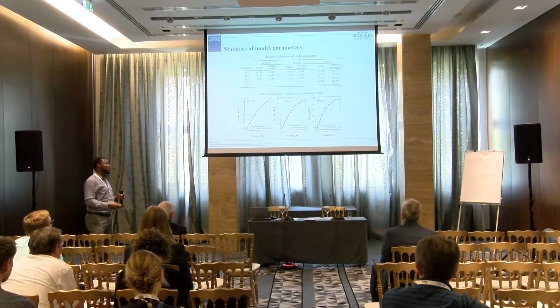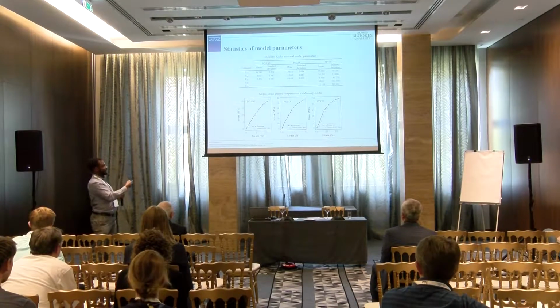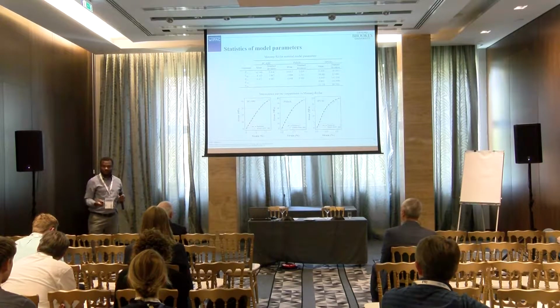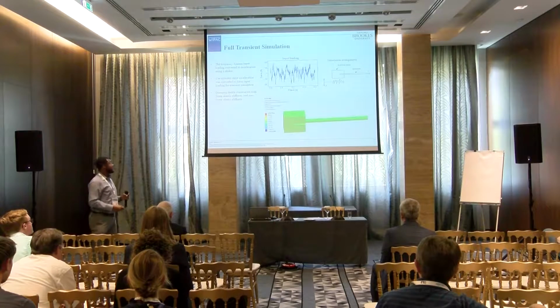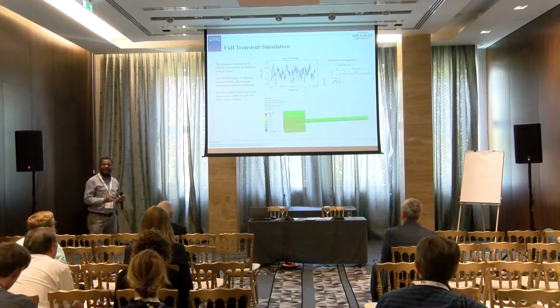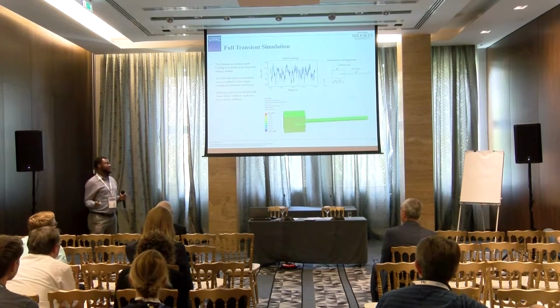So now we can use the elastic modulus of this Mooney-Rivlin model to construct our damping matrix, to model our response. And we did that. We constructed our damping matrix using linear and nonlinear Mooney-Rivlin, and tensile and secant modulus.